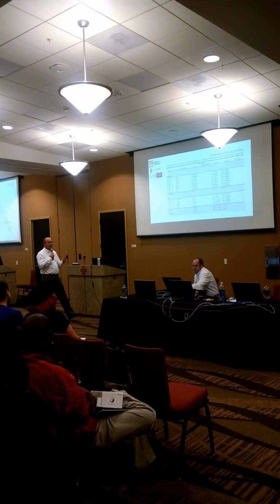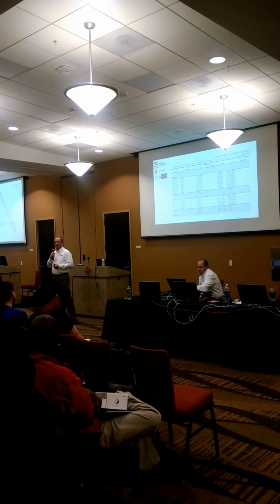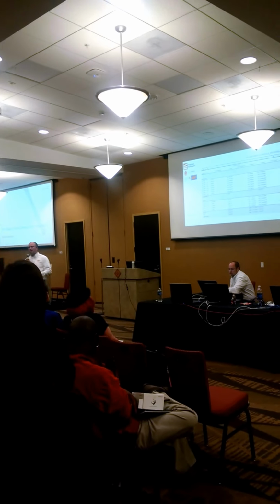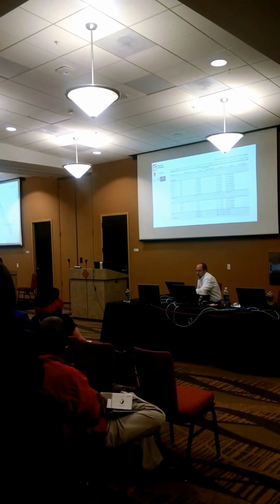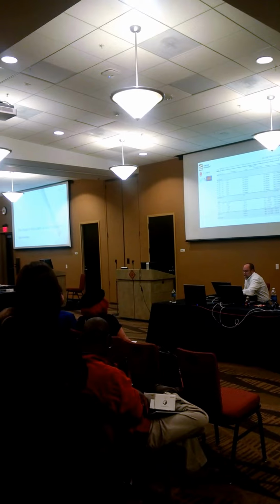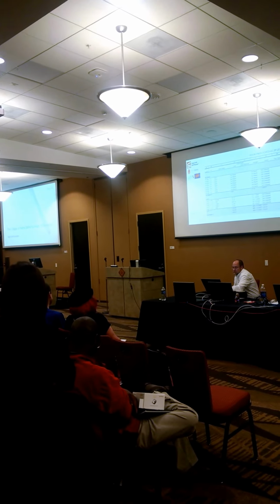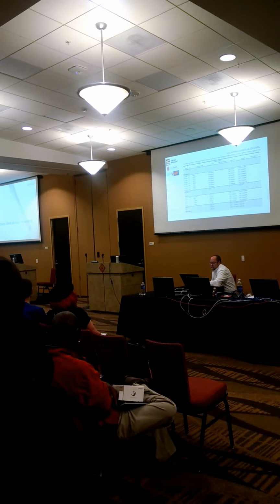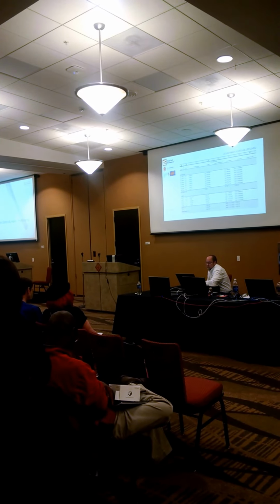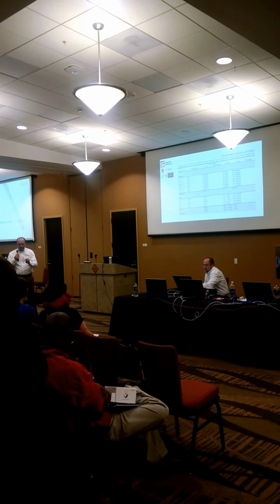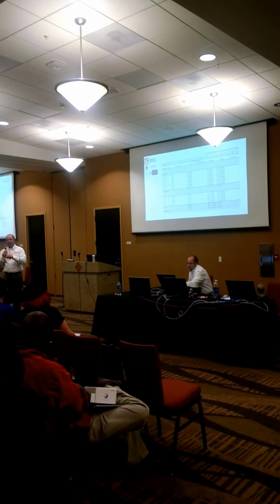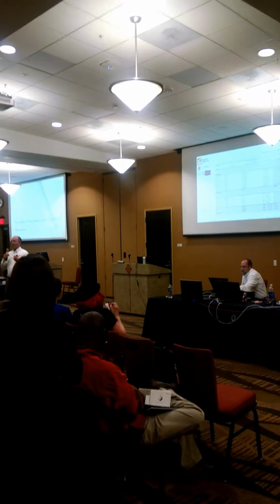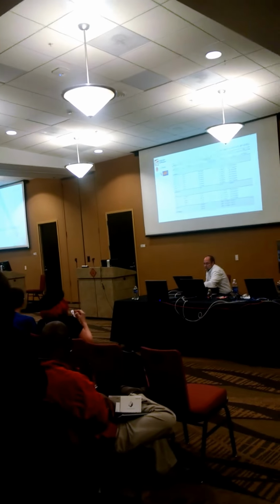Also, everything we do in Revit is automatically tracking different information, whether it's rooms, room numbers, square footage, finishes, data, whatever it is, it's live tracking it. So if we add a room or take out a door or put a new door in, it's going to automatically update it to every view, every location in the actual model itself. So we don't have to sit there, print out a set of documents and with a highlighter say, is that room placed, is that there, different stuff. It's automatically calculating it without having to do a save or a refresh or anything else.